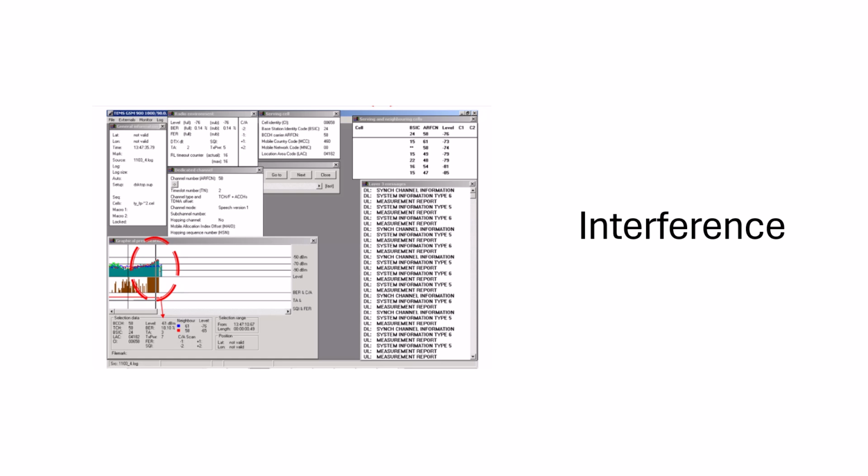Frequency scan for GSM: configure TEMS to scan the GSM band of interest, for example GSM 900 or DCS 1800 for downlink frequency. For each ARFCN, observe the power level across all channels. A channel showing unusual high noise or unexplained peaks may indicate interference from overlapping carriers.